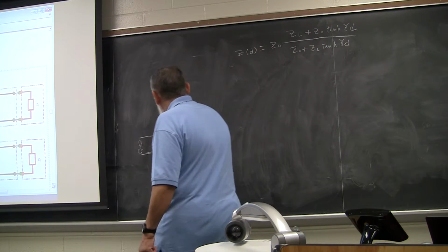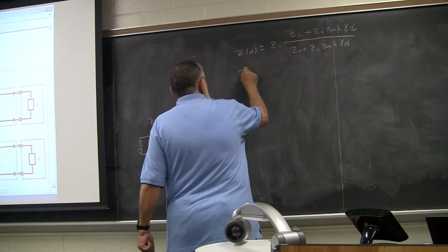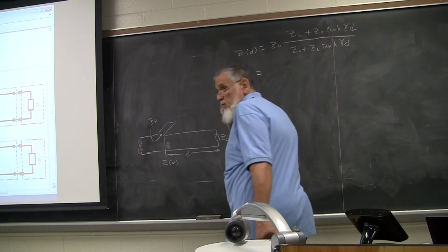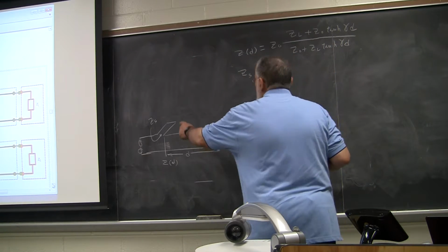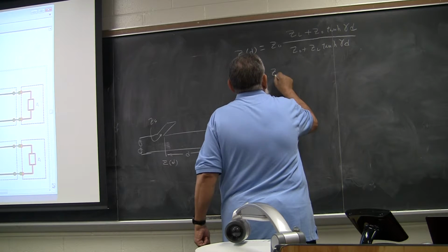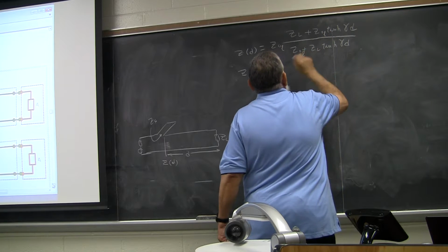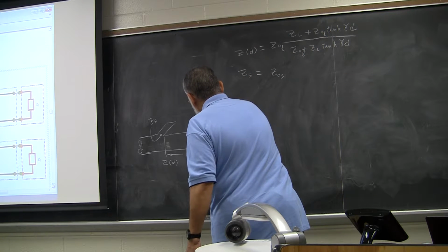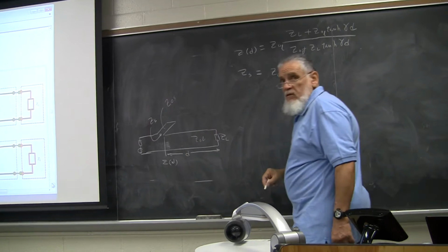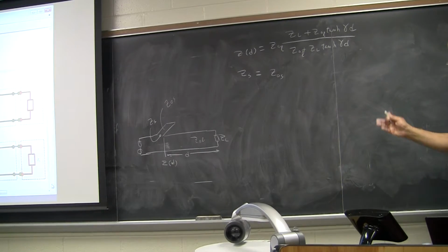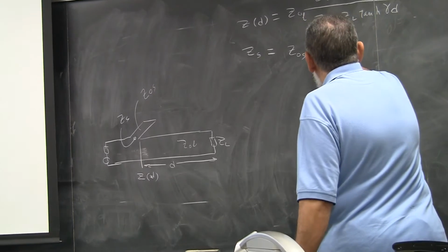And then the impedance of the stub, Z of the stub, is a similar equation, with Z naught of the stub. Now this is Z naught of the line, okay? Z naught of the line. Because the stub could be a different characteristic impedance, different dimensions for any reason, so we'll just make it general.